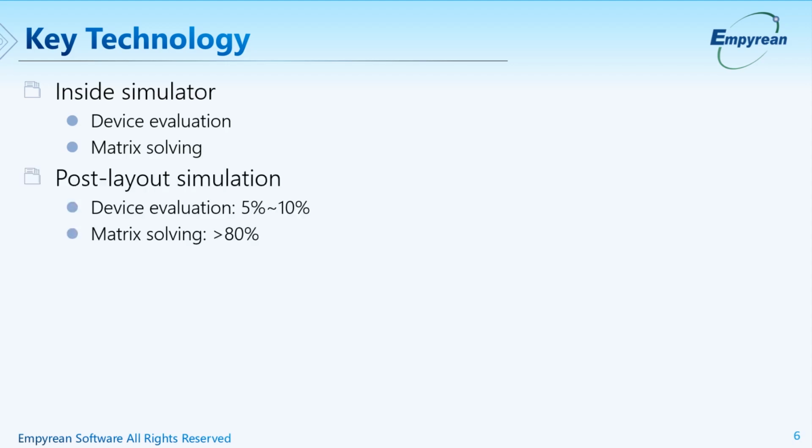So why can ALPS achieve 3 to 5 times faster than other SPICE simulators? You have to understand how a SPICE simulator works. Inside a SPICE simulator, there are 2 parts that are most time consuming. One is called device evaluation, the other is matrix solving. For example, in a typical post-layout simulation, the total time of device evaluation and matrix solving can make up more than 90% of total time. And you can imagine if we can greatly reduce this part of time, the total simulation time will be reduced.